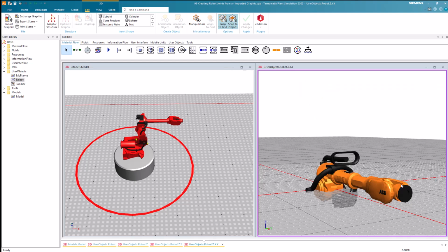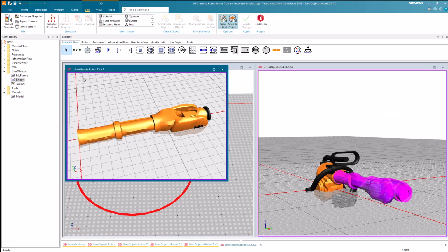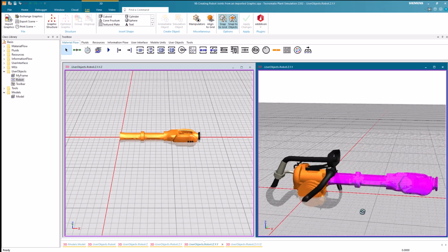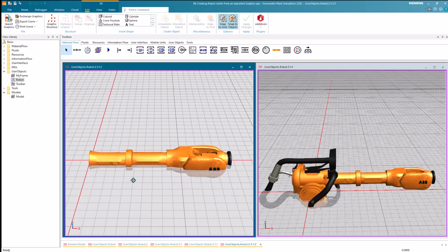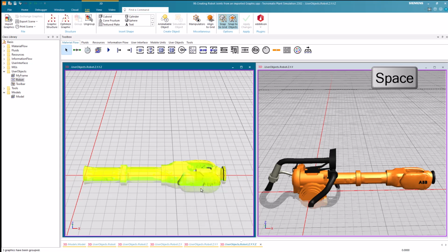After clicking OK, we open the joint in a new 3D window. Here, it becomes evident that the joint is not correctly positioned. It aligns along the x-axis. To rectify this, the initial step involves grouping all graphics. Subsequently, we access the transformation dialog.